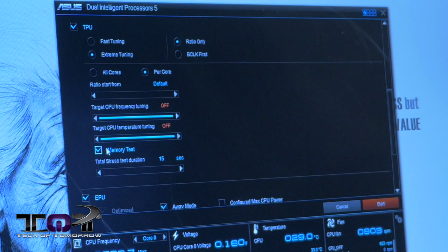And this is an important consideration because sometimes when users dynamically overclock their system, they don't realize that the CPU frequency can affect the actual stability of memory. So sometimes you might have a CPU that can do 4.6 gigahertz, but it can't do 4.6 gigahertz and DDR3 2400 at the same time. Yes, correct. It might only be able to do 4.6 at 2133 at the same time, versus at stock, it could do stock frequency and 2400.